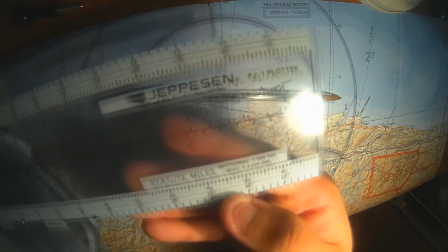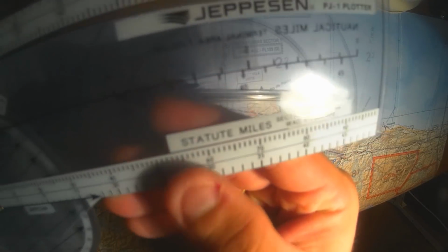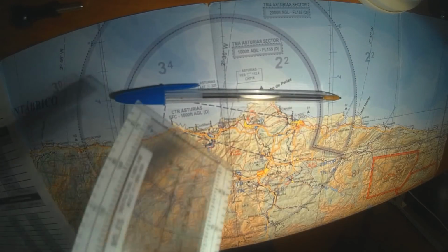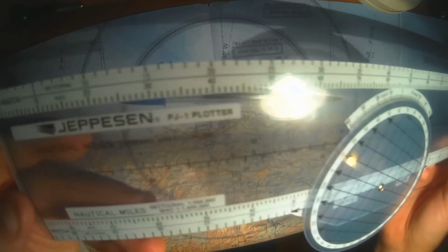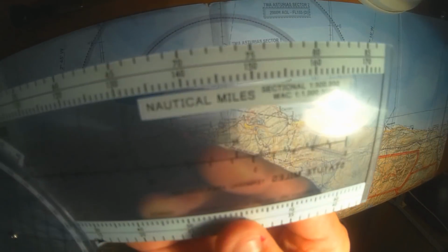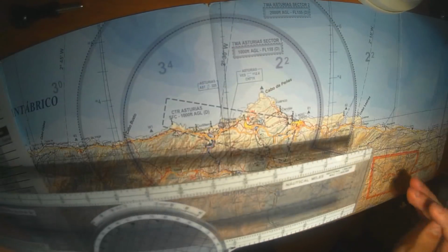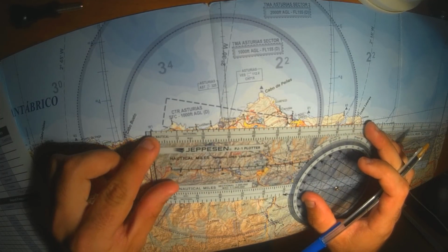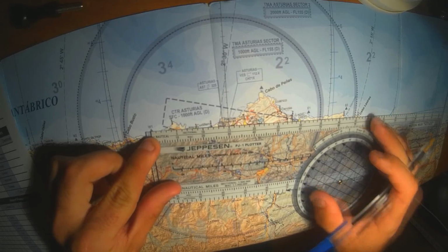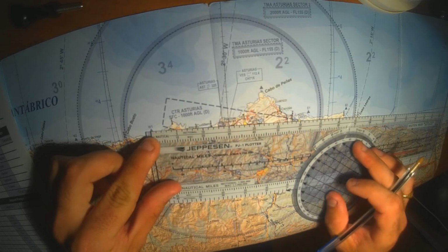The next column is about the course, which is the straight line between 2 points as measured over a map. To calculate the courses of our flight, we use the plotter instrument. This ruler helps us determine the distance in both statute or nautical miles, but also the true course. This instrument acts like a ruler, so we place it to measure the distance between our 2 points.